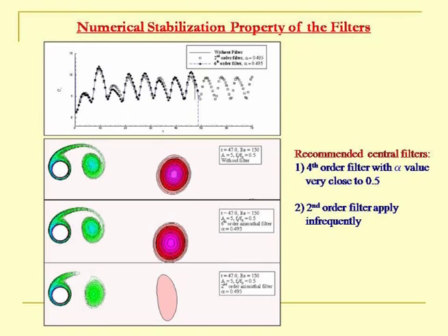Sometimes you have to really enlarge your window of observation to make sure that things are all right. Suppose I had stopped at 40 and said, oh, I could get a good solution, and presented such results. But here it is clearly seen that at t equal to 47, all of a sudden the CL nosedives and the solution blows up. Why does it do so? That is given in this vorticity contour plot. This is one of the vortices that has been shed in recent times, but prior to that there was another vortex shed from the lower side, which convects downstream.